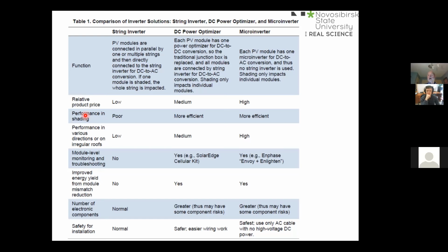I meant to point this out: the photo of the PV system that I showed at the start of the lecture yesterday shows the shade from one row of modules just about to touch the bottom of the row behind it. So you do get a little bit of what's called self-shading on a PV farm, but you very rarely get any other form of shading. You'll never see a PV farm with trees around it, because trees obviously cause significant shading.